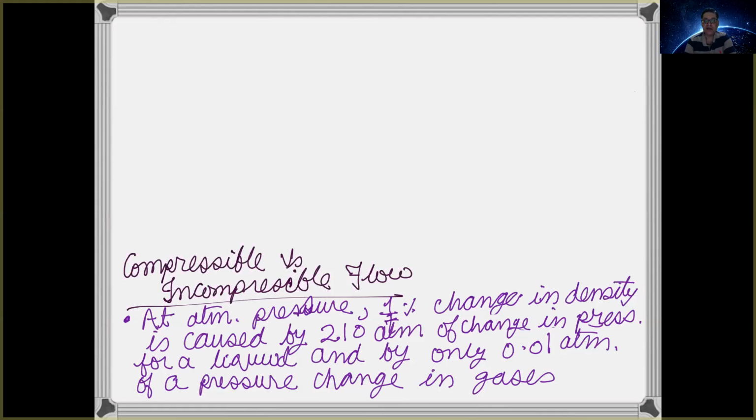The density is not varying with space. Whereas for gases, if the velocity in the flow domain is very large, at high speed gas flow, the density variation in the flow region is found to be large enough, and in those cases we consider the density variation. However, at low speed gas flows, we still consider the density variations as negligible.